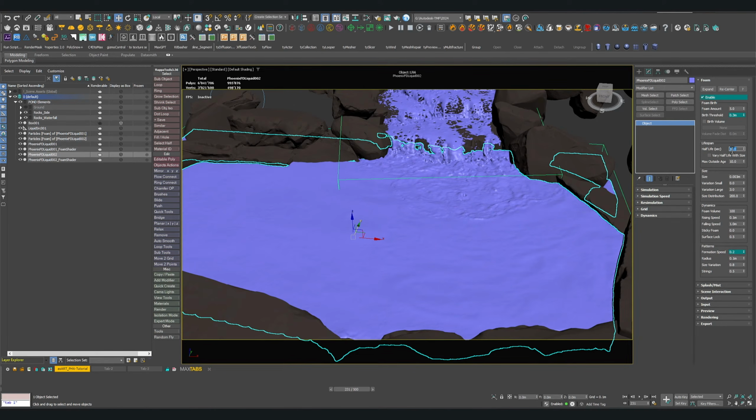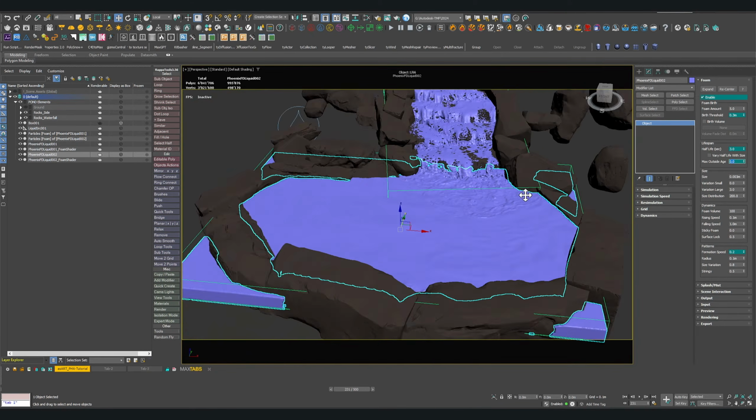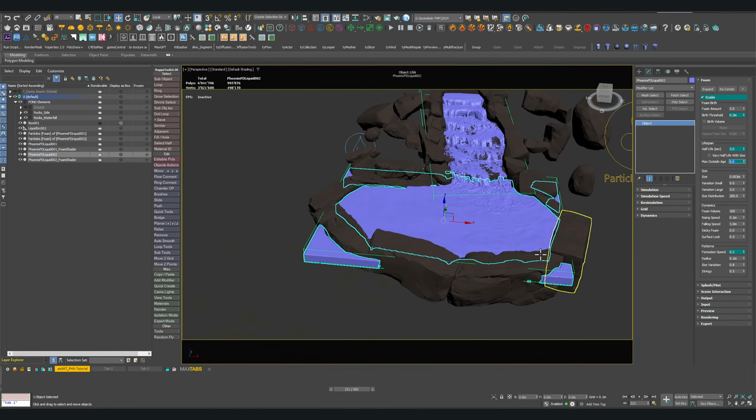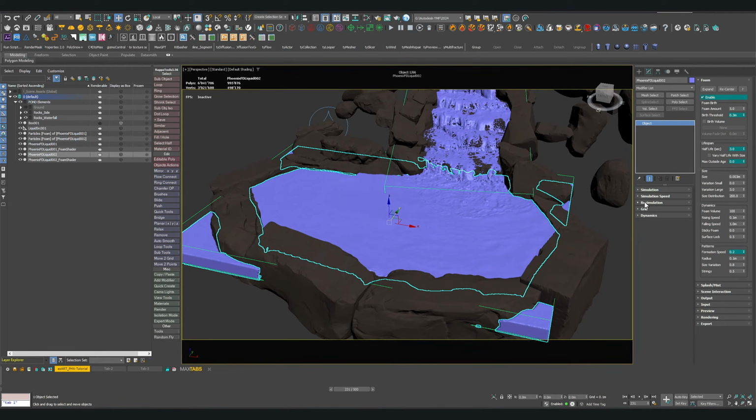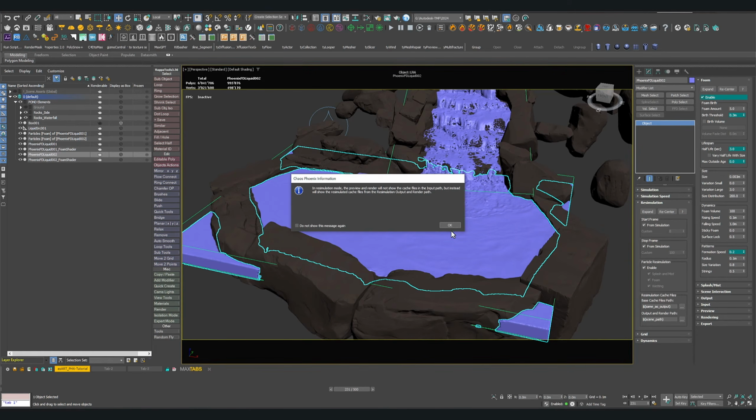So I'm going to lower this. I'm going to bring it down to maybe 3 seconds, so they're not living that long. And maximum outside age, I'm going to set to 0. I don't want any particles to go outside of this grid. So now let's activate resimulation for our second simulation as well, which is here. Say OK, uncheck splash, and then change the output path.